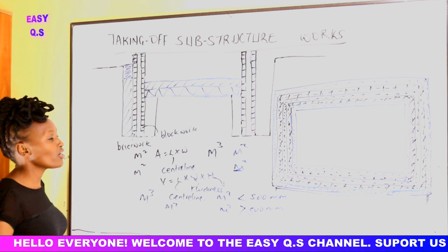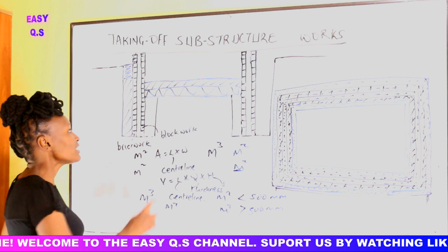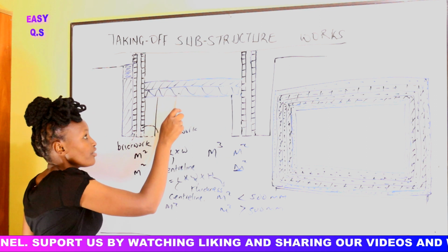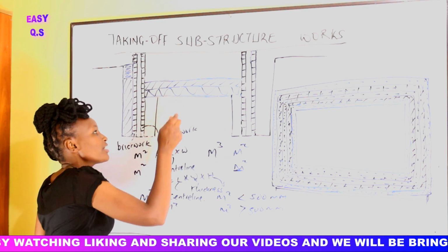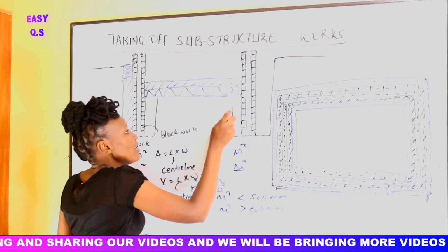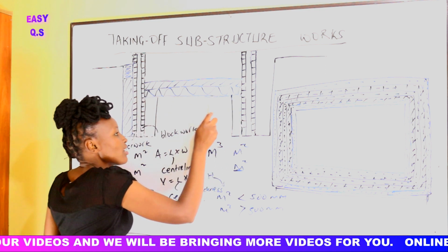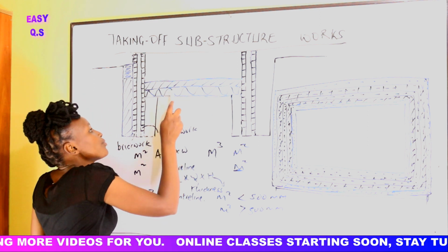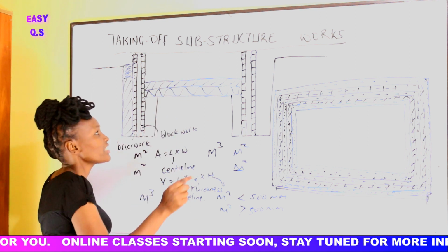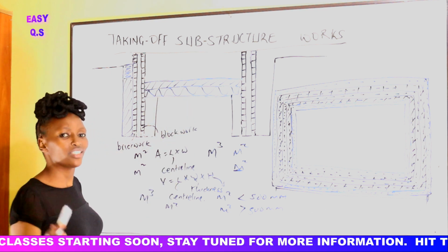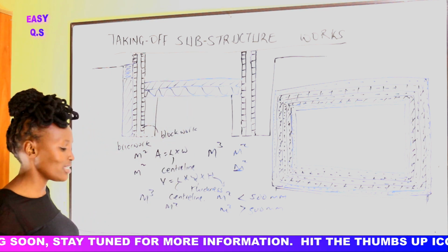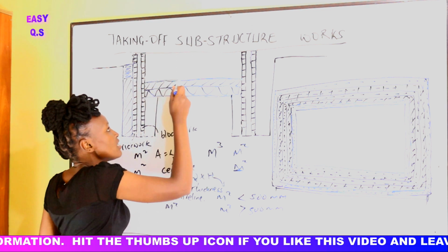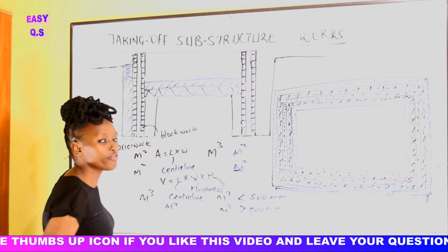So the thing that you can observe clearly is that this area where we did the hardcore, the area of the hardcore, the area for compacting, first of all we started with compacting this area. We compacted the ground inside the house, then we laid the hardcore, same area, then we compacted the hardcore filling, same area, we laid the floor insulation which is in the same area. Now we shall do the damp proof membrane on top of the insulation to prevent any moisture from coming up.